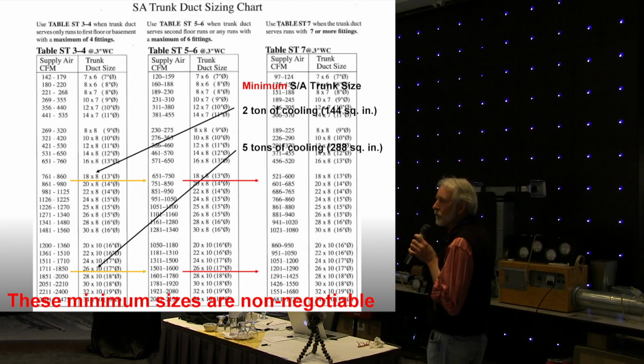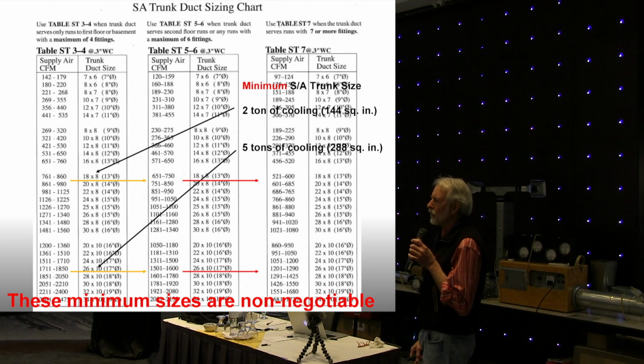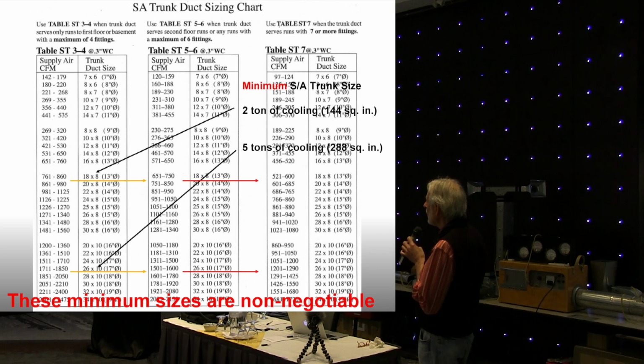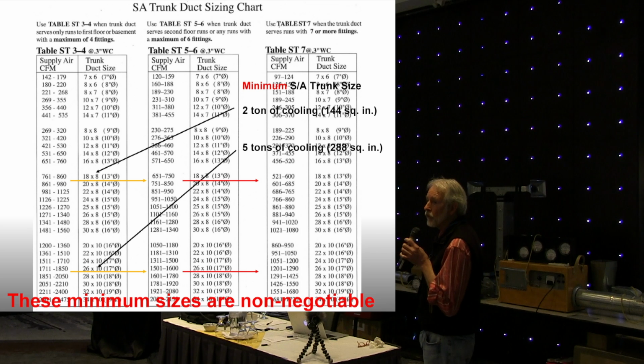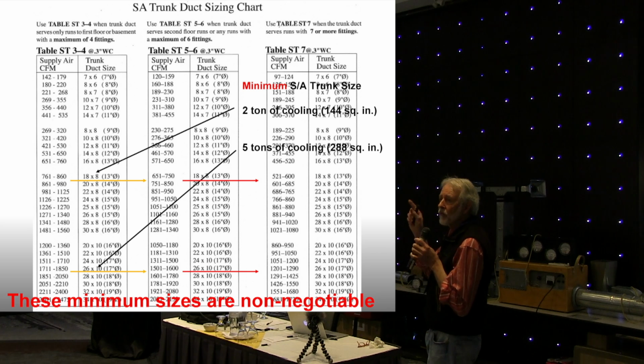And if we go back to very simple tables, Quality First has tables. They're just beautiful. I use this table every day for 25 years. It shows in a very simple duct system, which means there's 3 to 4 turns. So it's a very simple system. The ductwork there was capable of somewhere between 760 and 860 cubic feet. What's needed to do the job had to be right up here, minimum, but it really should have been up here around 2,000. So I made a boo-boo in that line position. But the net result is that the duct that was there was half that of what was needed to do the job.